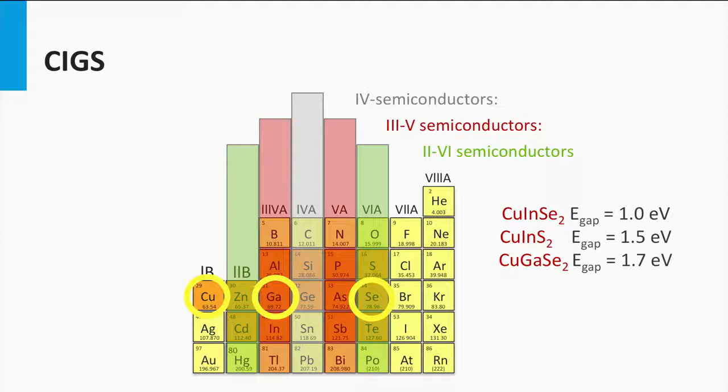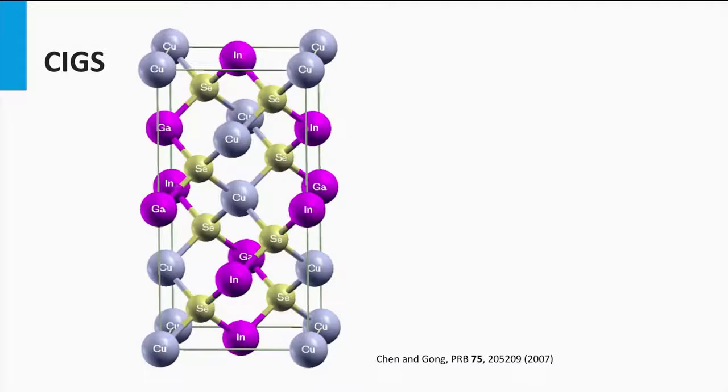The CIGS material is a direct band gap semiconductor material. Therefore, it has a large absorption coefficient. It requires only a thickness of 1 up to 2 microns to absorb a large fraction of the light above the band gap. Typical electron diffusion lengths are in the same order of a few microns.